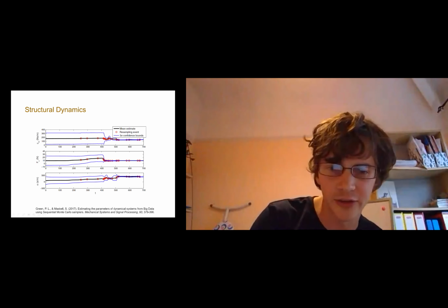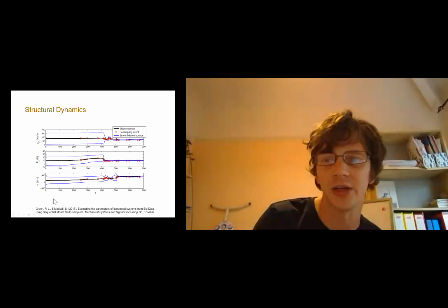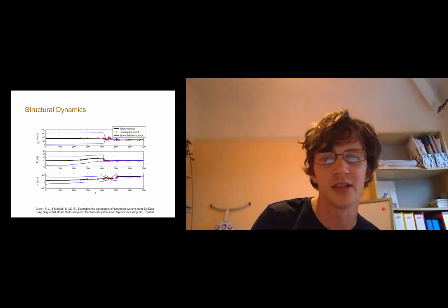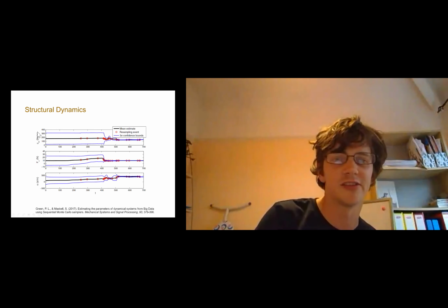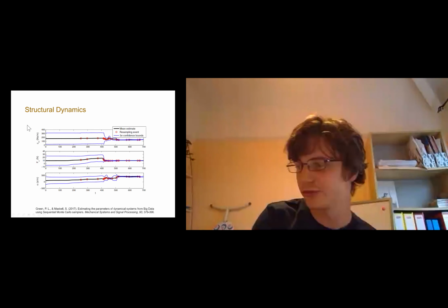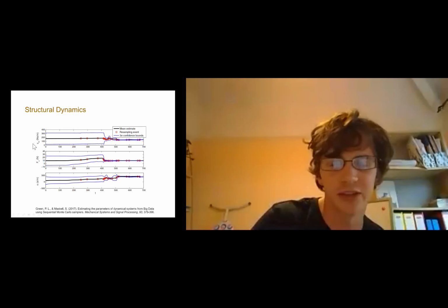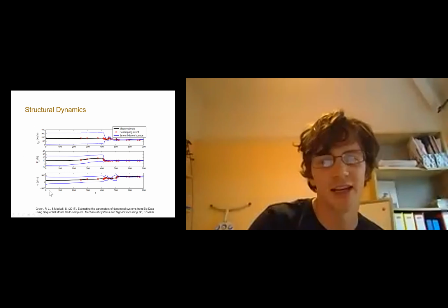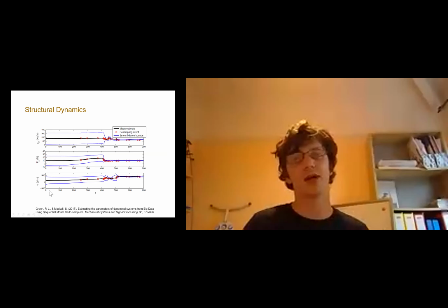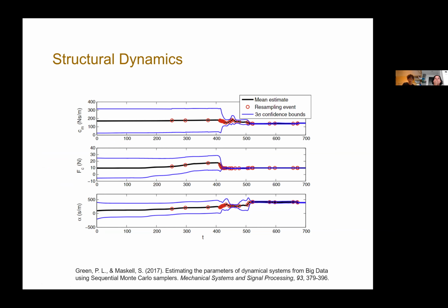So I think this is the first thing I wrote when I got to Liverpool, and here it is applied to the system from Southampton. We've got 3 different parameters. These are all parts of friction, because friction is really hard. Hard to measure those parameters directly often. And on the x-axis is time. So what we're doing here is we're analysing a time history of the dynamical response of this system, and about this time index, 400-ish, is where friction really kicked in.